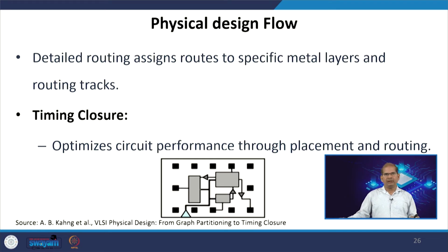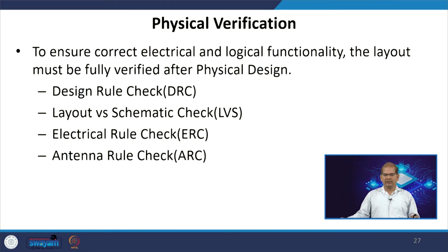Then you have timing closure, which optimizes the circuit performance through placement and routing. During the design phase we defined some timing, and we need to meet that timing through optimizing the placement, routing and all these optimizations. So, timing closure is one of the most critical parts of your VLSI physical design flow. Then we have physical verification: how can we verify our design?